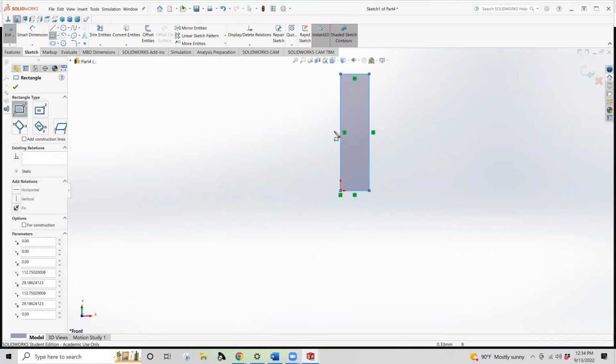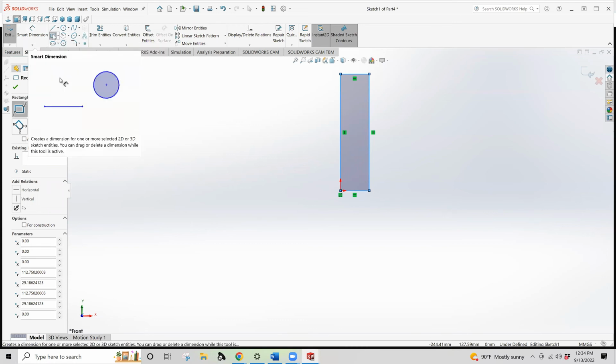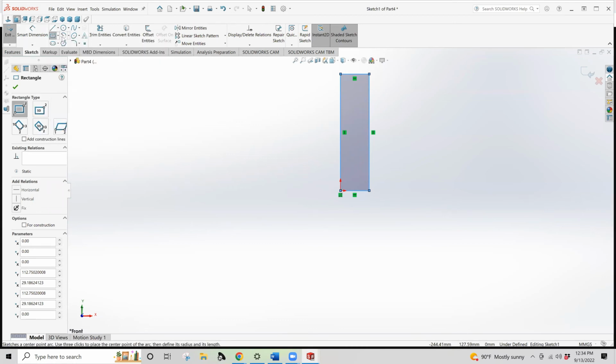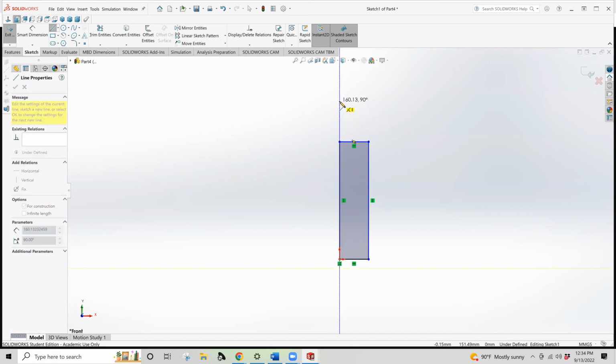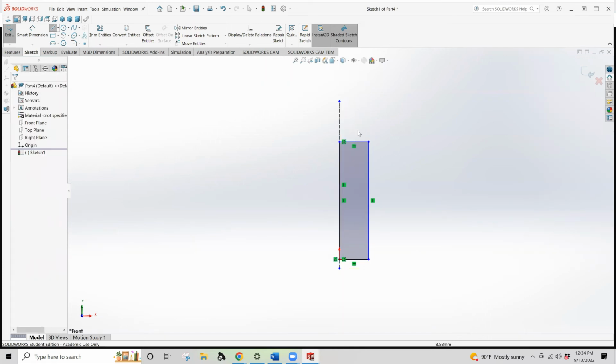So I might have kind of a tall, narrow aspect ratio. We're going to set it up for revolve. So we're already thinking ahead of that. And we're going to do a center line. We'll do a little more geometry work here.